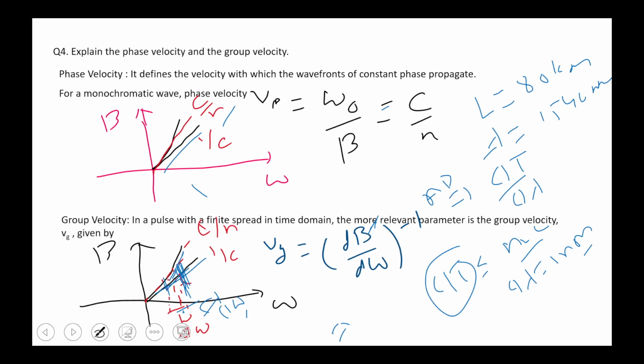So you are given L, the length of the fiber, and from the refractive index you can calculate delta as n2 minus n1 by n1. L is given, and D you have to calculate for the accumulated dispersion. Delta T you can calculate from the above equation, and delta lambda I have already mentioned, 1 nanometer. So from these things you can calculate the value.